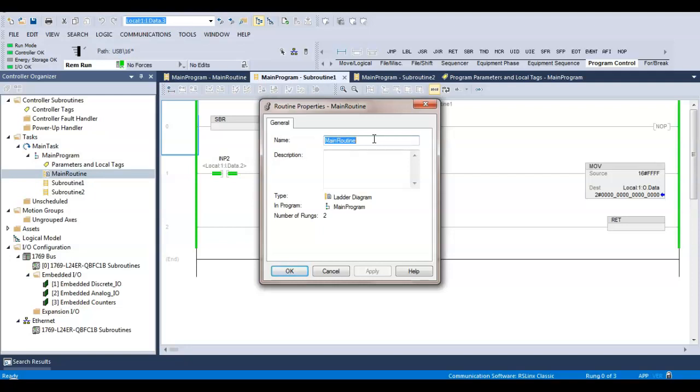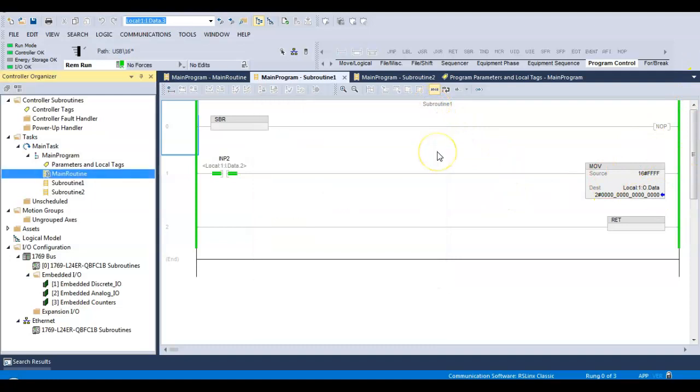So all these things do that. We'll look at other things that go along. This is a real simple program, and like I said, all this is in there is for control. Just another option. But the inputs are still scanned, so you'll notice even though the subroutine is not running, the inputs are scanned first. But it doesn't update the outputs unless the subroutine runs. So any more questions? This is a good question here.